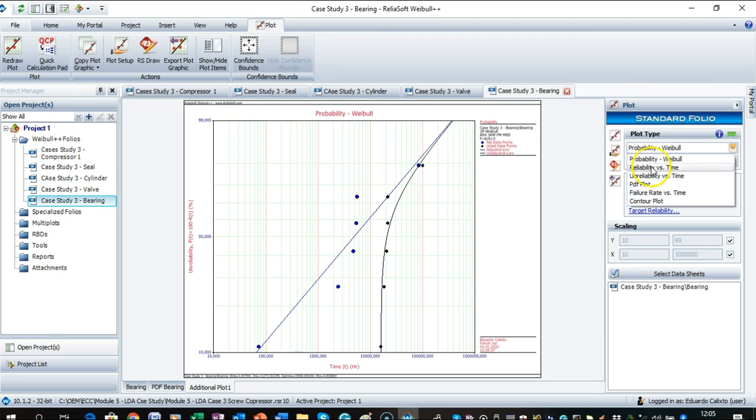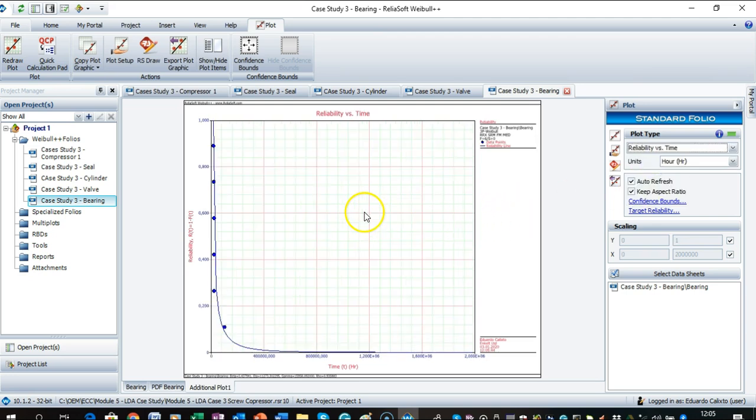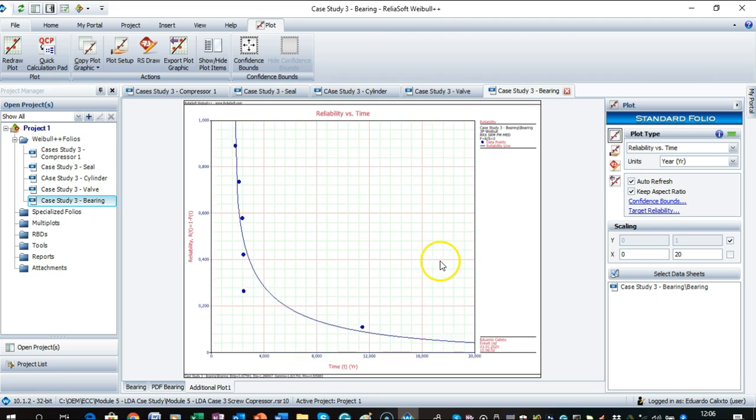So let's plot the reliability function. There will be a period of 1.5 years with 100% reliability, and after that we get a very fast decrease with failures. So if we put each adjust here for 20 years of the failures, that's what we've got. That's the reliability function. So until 2 years, or 1.82, we have 100% reliability. Then reliability goes down very fast, and that is the reliability.